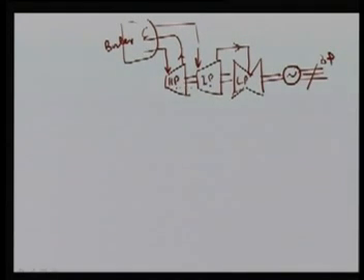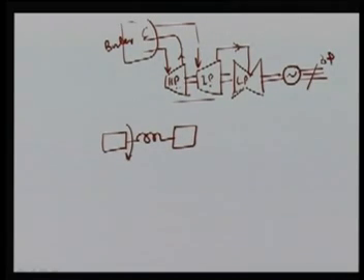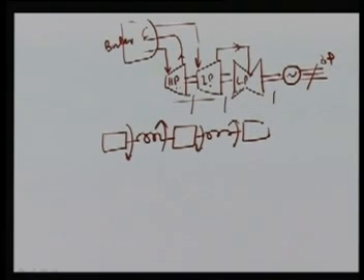So, they behave just like this example here. One mass is connected between a spring and another mass. Here it is rotating and the other is opposing, and then finally another mass, and so on and so forth. If we analyze, we will have some critical frequency corresponding to all these masses. So, we will get the 1st, 2nd and 3rd frequencies arising, and those are called the torsional modes of frequencies, and that is some oscillation.